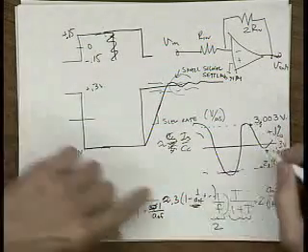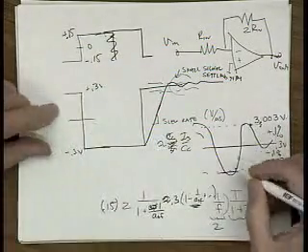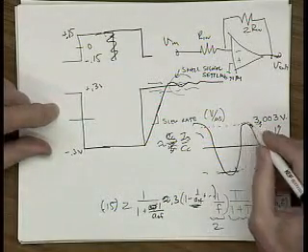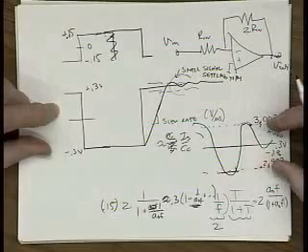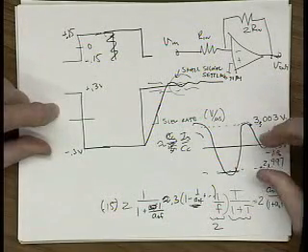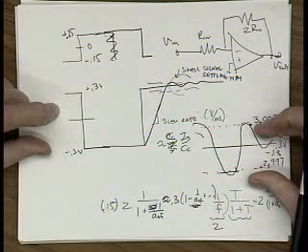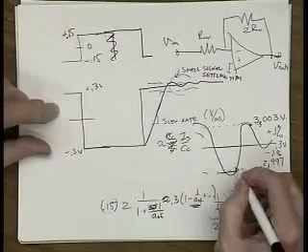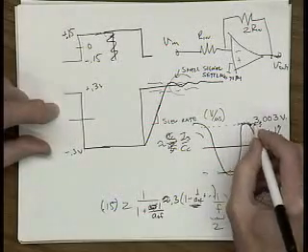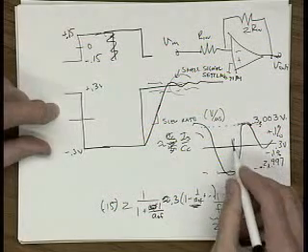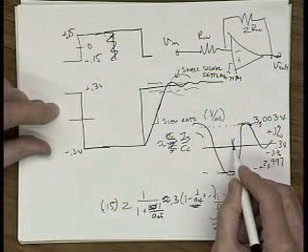Now, the settling time is defined as once you enter this bar, the plus or minus 0.1% around your final answer, and stay in there, then that's the settling time. So it's the last time you entered. Like here, let's say this is just below there. So this entered right at this point. It's at this time that we call the circuit settled.